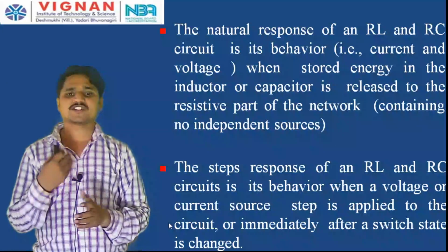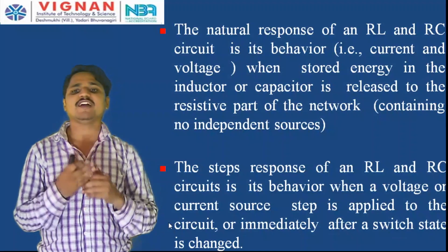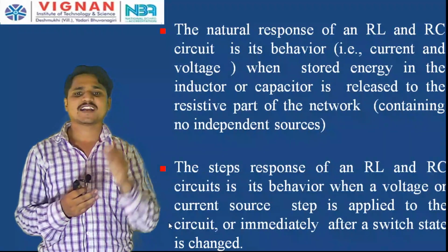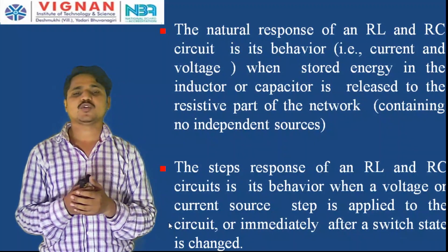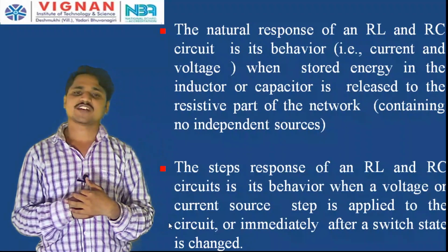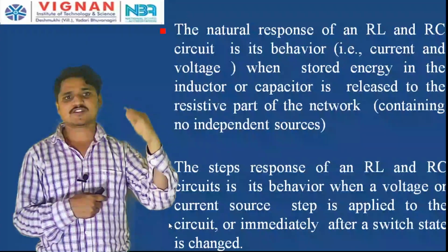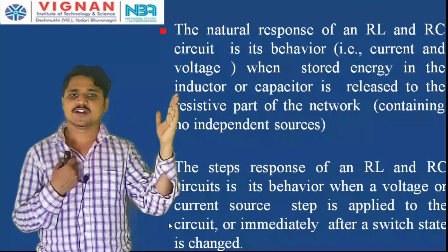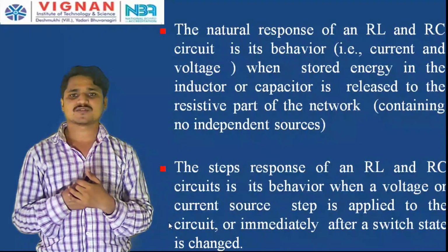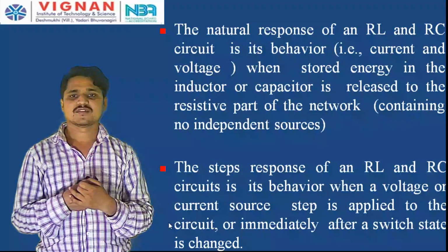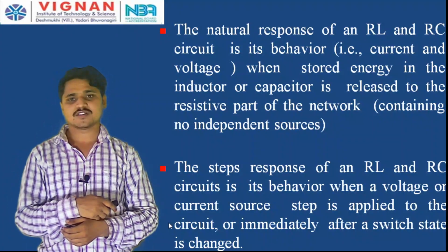Now, what is meant by step response? The step response of an RL and RC circuit is its behavior when a voltage or current source step is applied to the circuit, or immediately after a switching state is changed, that is, switch opening or switch closing. Immediately after the switch is opening, what is the response? That is the step response. Immediately after the switch is closing, what is the response? That is also called the step response. So, this is the definition of natural response and step response.